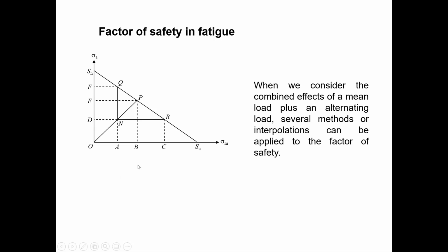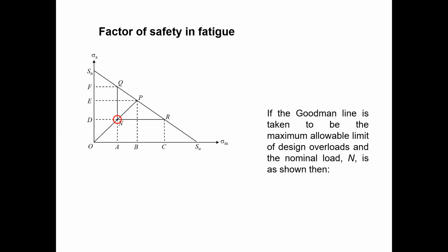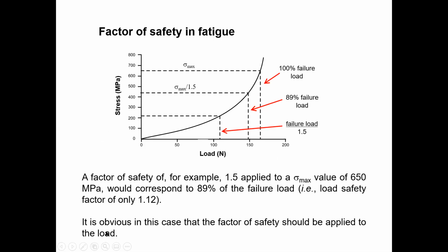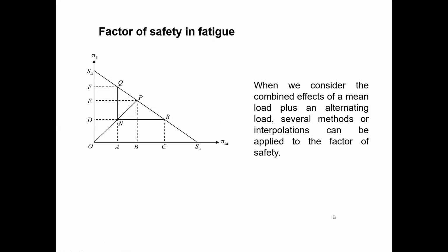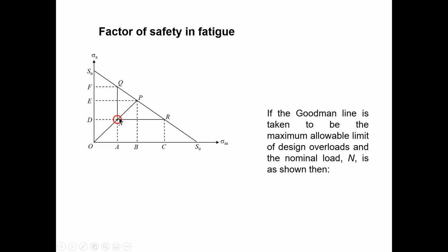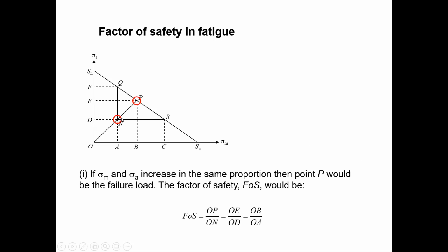Are we clear? Yes, sir. Okay. So as I told you, you need to keep it in mind in here. Even though this particular graph belongs to stresses, we need to consider the load value around here, the maximum stress load value. Don't use the stress value. So load value in here and load value in here. You need to get the ratio between these two. It is the factor of safety, but you don't need to find those coordinates. If you have this x-axis coordinate, that is enough.